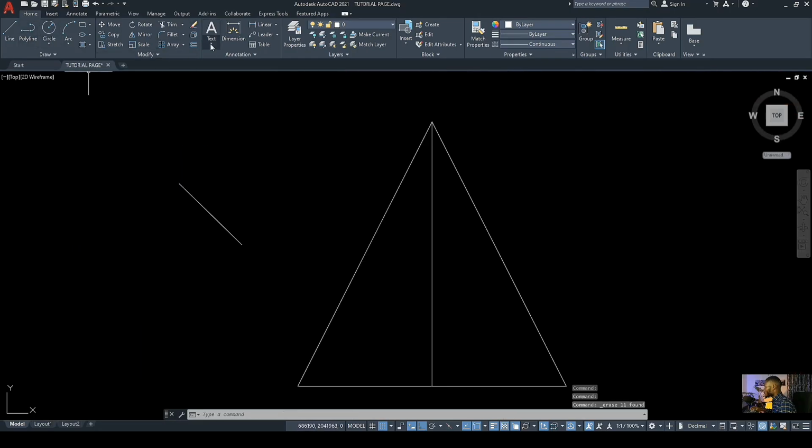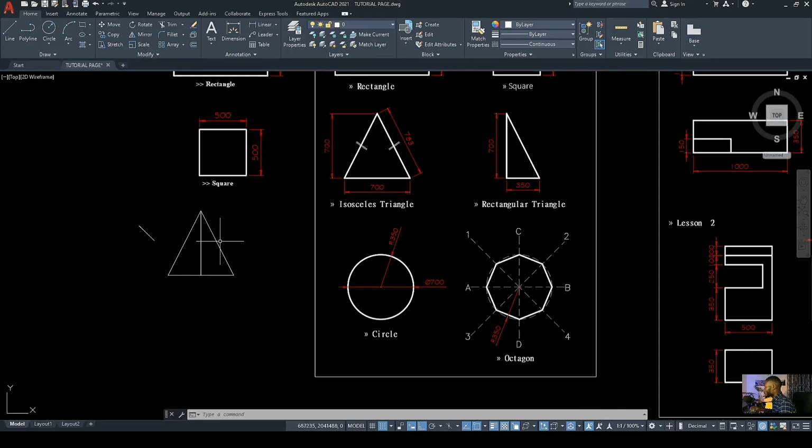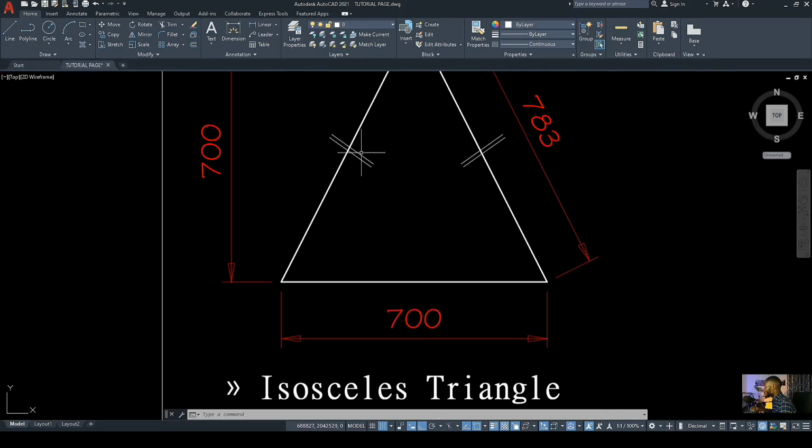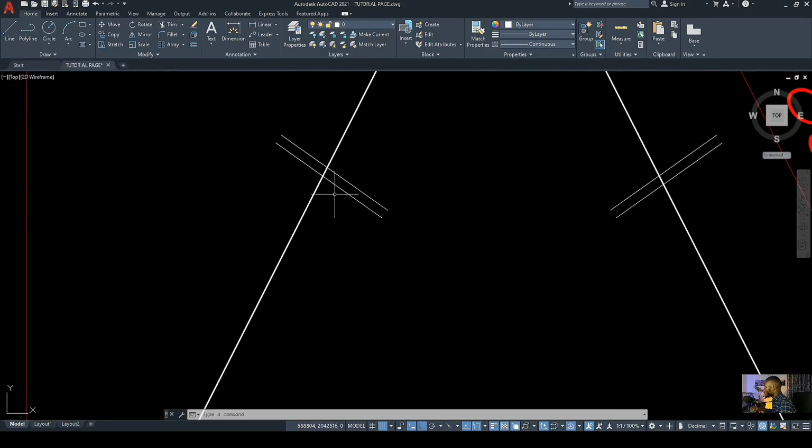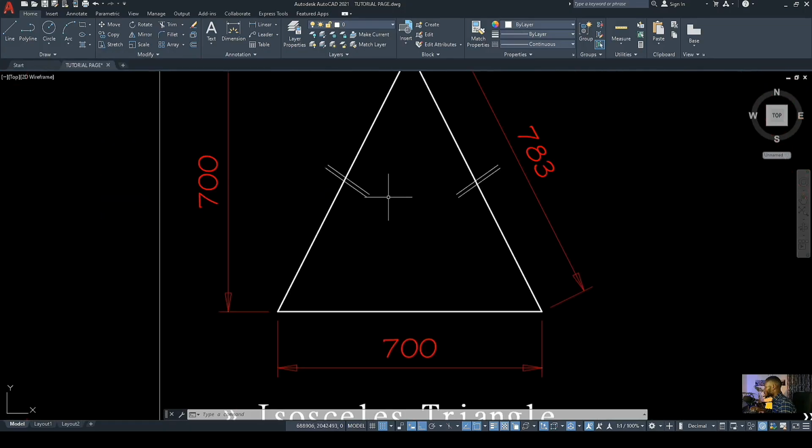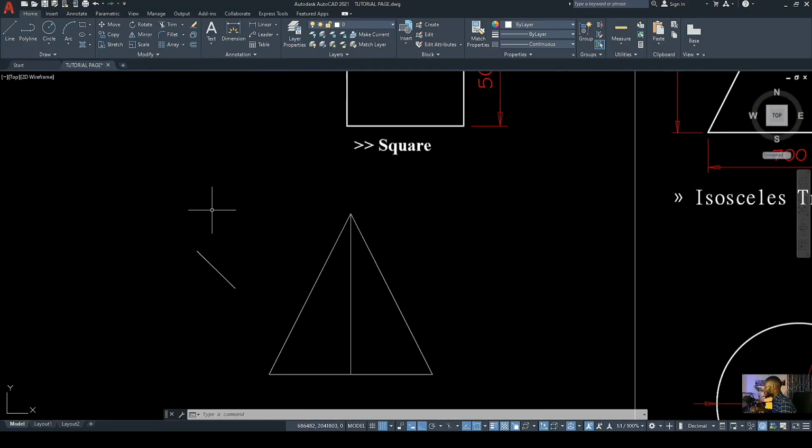So now you pick your offset tool. This brings us to offset. If you check the line closely, you see that there are two at an interval, same line being displaced at an interval. So what we are going to do here is to pick our offset tool. The offset tool enables us to displace a particular line to a given distance interval.